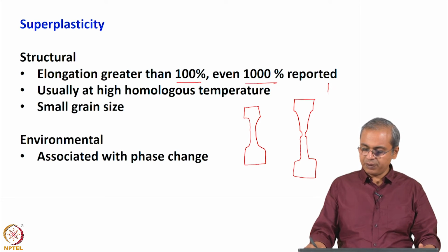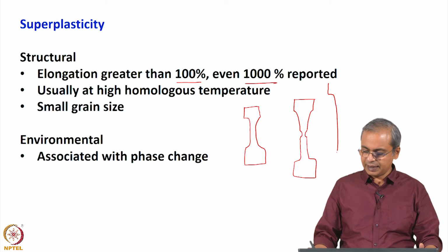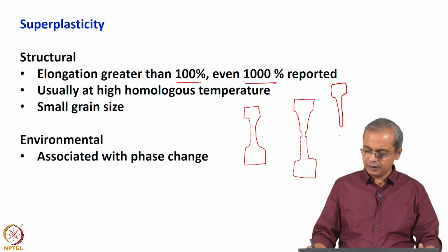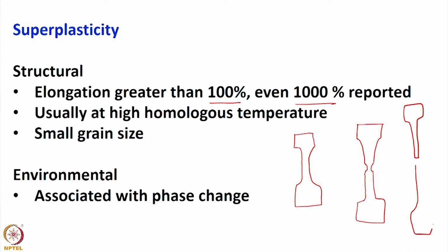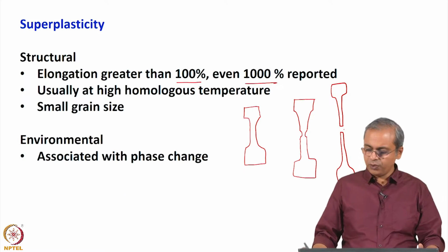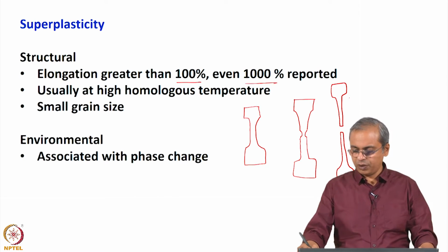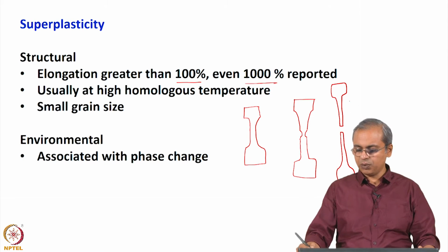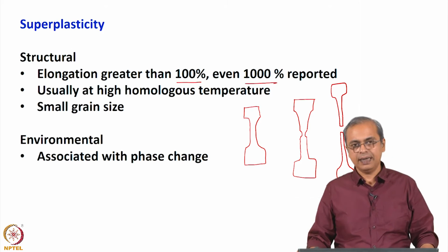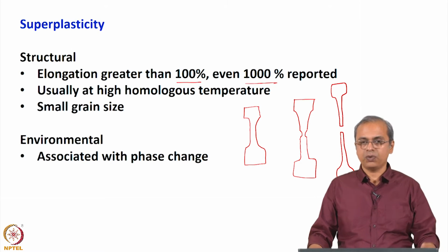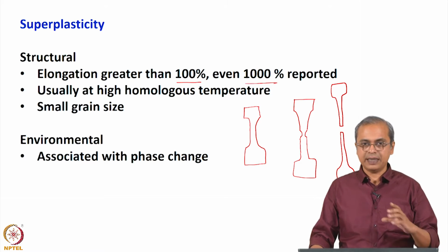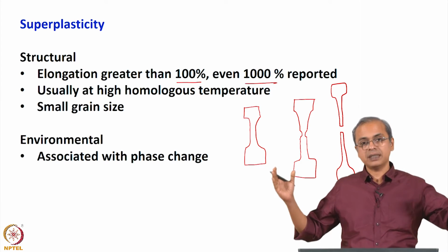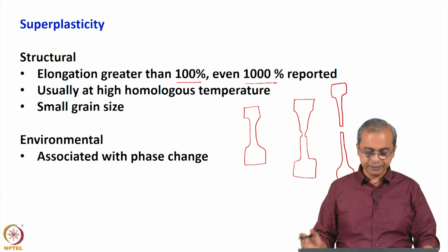So finally the sample will be something like that. Actually I need to change that. So something that looks like that, where finally you have a sample that is fractured, right. So you look at the final elongation that you have accomplished. So you have some gauge length, and then you look at the final length of that sample relative to your original length for that region, and then that gives you some idea of how much it elongated before it failed.